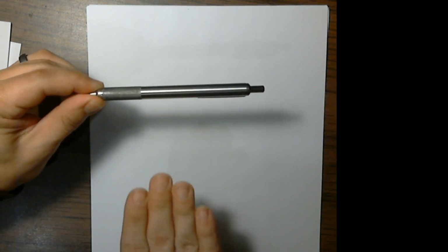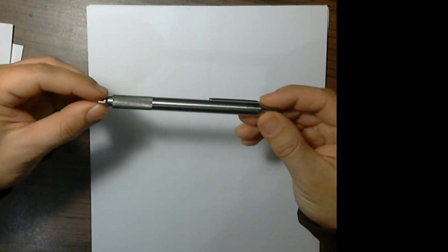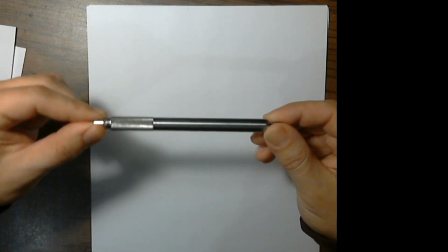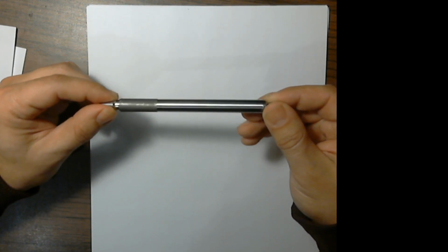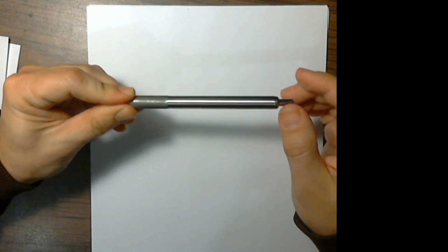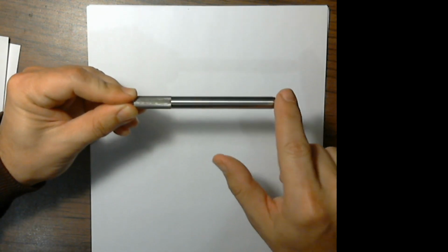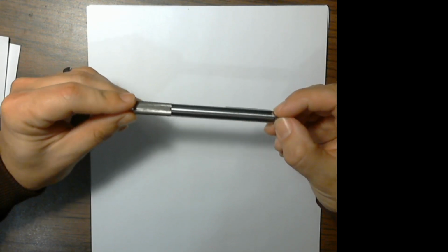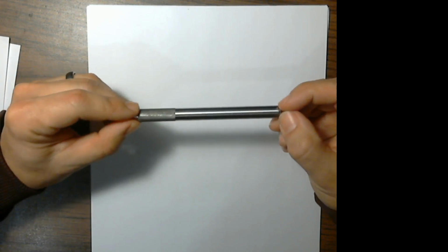And as air flows over the hot surface it is cooled. Well, the surface is just heated electrically. It's just a chunk of metal with electricity going through it. Well, it's a little more than that. It's a metal whose resistive properties are very precisely known. So as I push electrical current through the wire, I can detect everything. I can know the voltage across the wire, I can know the current through the wire, which means if I'm a controller, if I'm a computer watching this, I can know what its electrical resistivity is. So I can know the heat I'm adding to the wire, and I can know its temperature.